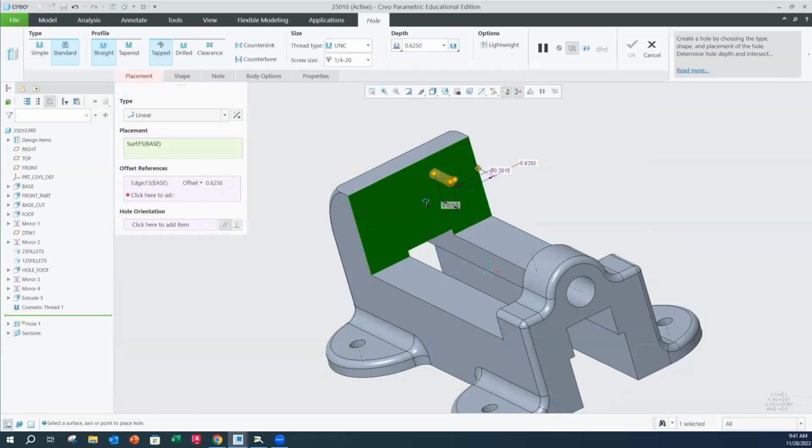And then the other broken diamond, I'm going to go down to the bottom here. I'm going to release when it closes over that edge. And now you'll notice that I can either double click here. Now be careful when it's over the model. I did this earlier and when I double clicked this, it actually selected the edge and then all of a sudden my hole moved, okay? So I'm going to select it over here in my menu and I want this to be 1 inch, okay? So now it moved that to that position.